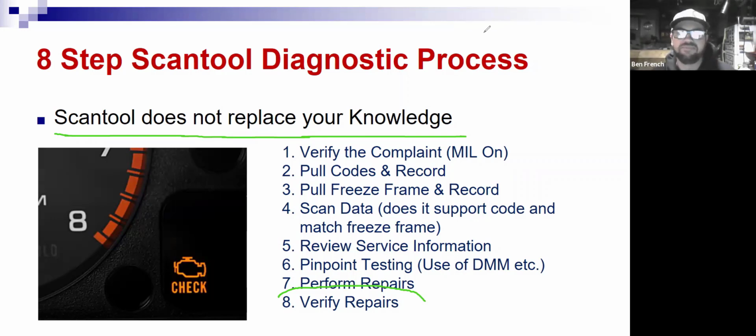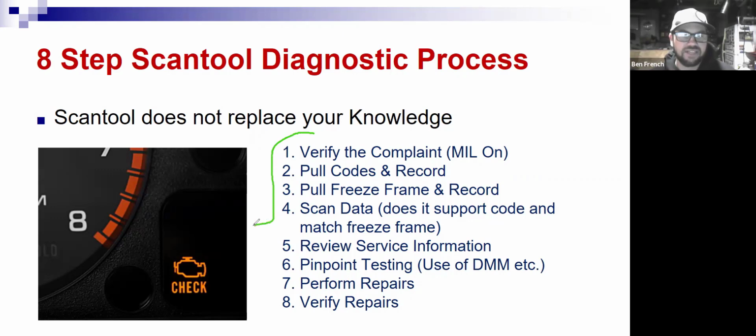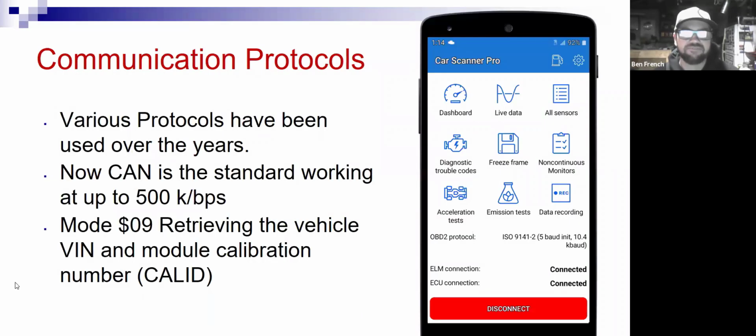Sometimes these vehicles can be pretty tricky with their diagnostics. So don't forget the basic process of verifying the complaint, pulling your codes, and always recording stuff, writing down your information. That's what you want to do when you're trying to diagnose a modern vehicle.